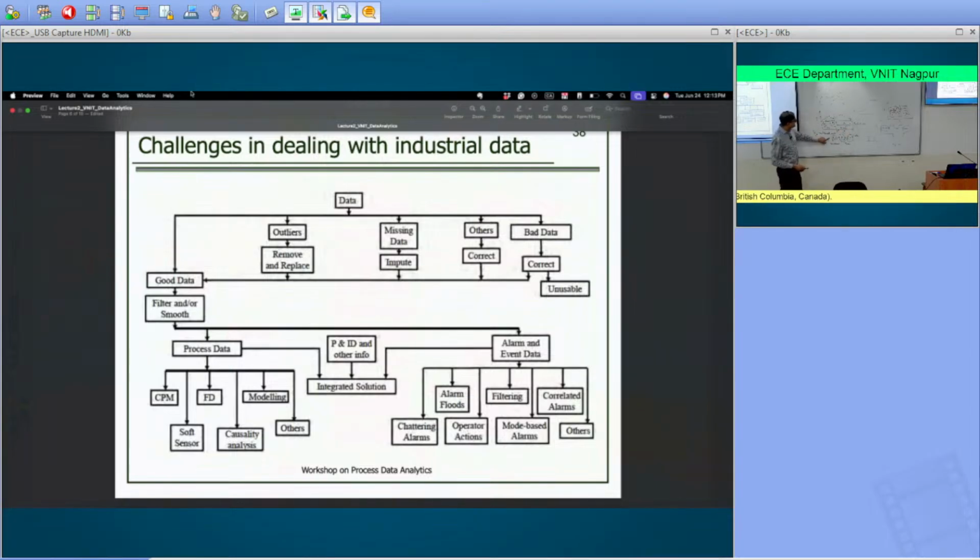The other problem is, at t star, I have the measurement, y t star. But I know that measurement is corrupted with noise. And the question I'm asking is, if I have all of these past values of y, they must have information about the noise, the type of noise that my sensor is generating, right? Then can I use all of those measurements to come up with a really good estimate of this y bar t star? It turns out that there's an optimal way of doing that.